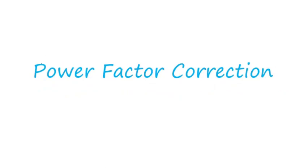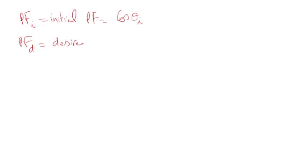Let me start with some definitions or terminologies. I'm going to use power factor I, which is the initial power factor before correction, equal to cosine of the initial angle theta I. The power factor D is the desired or final power factor, cosine theta D. So this is the initial power factor, and this is what we want to correct the power factor to.